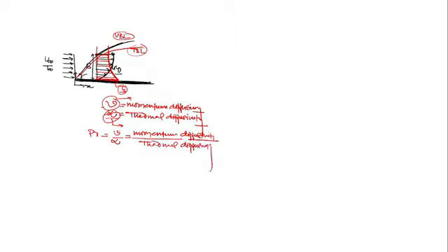Now tell me please, if momentum diffusivity dominates over the thermal diffusivity, or if momentum diffusivity is faster than the thermal diffusivity, then what happens? Which boundary layer thickness is more? If momentum diffusivity is faster than thermal diffusivity, then the variation in the velocity extends to a farther distance in the y direction as compared to the temperature variation.